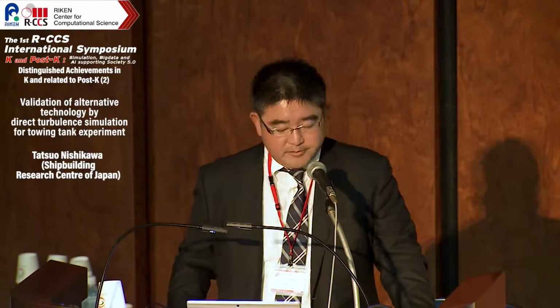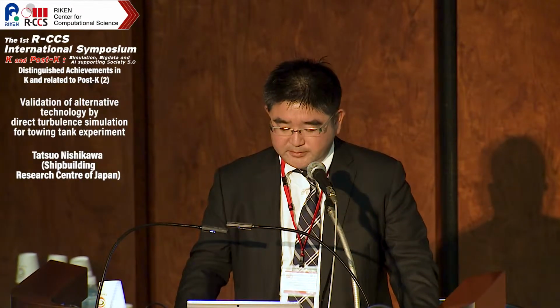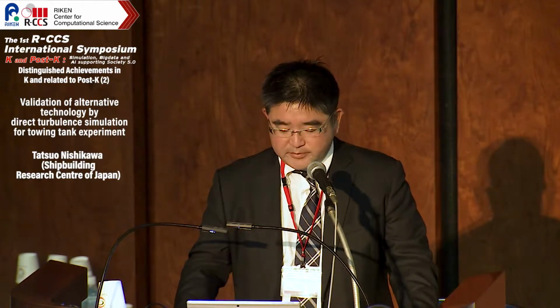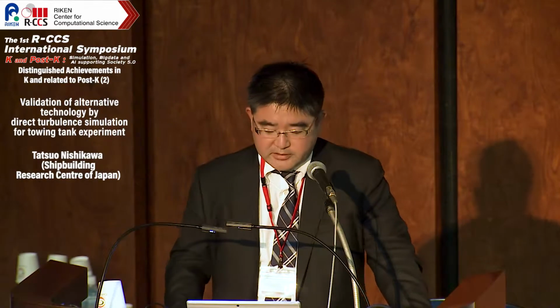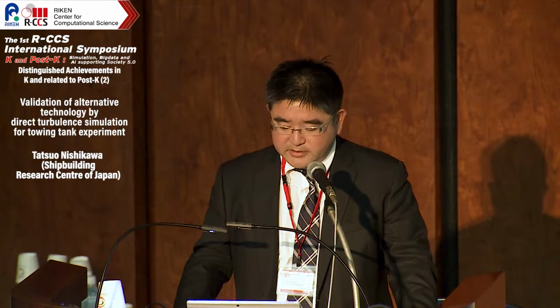In the business negotiation, a ship designer defines the main dimensions such as length, draft, breadth, depth, weight and speed. They roughly estimate the necessary power from their database, and they calculate up to 100 types of ships by CFD.